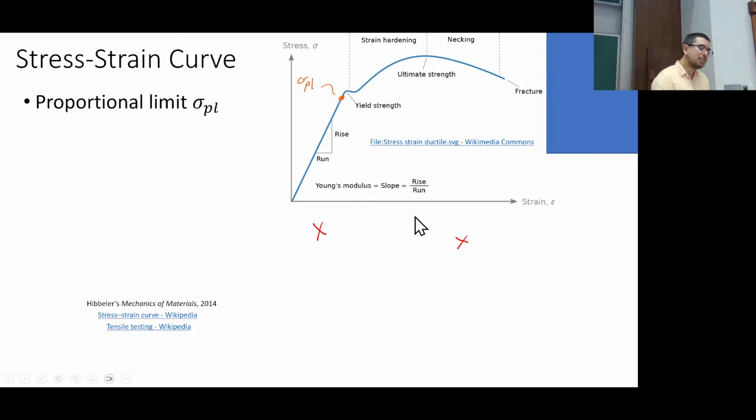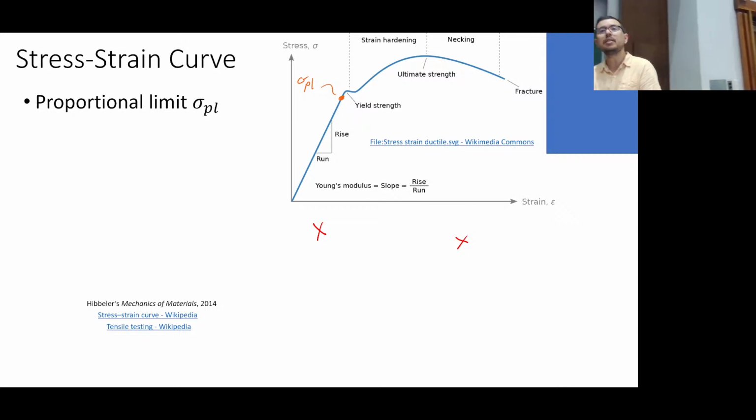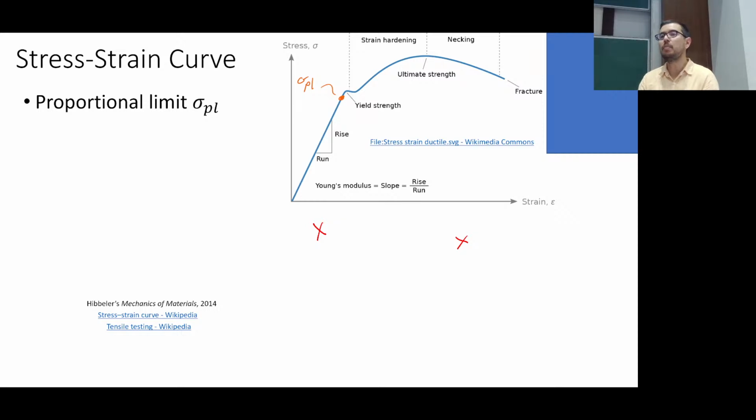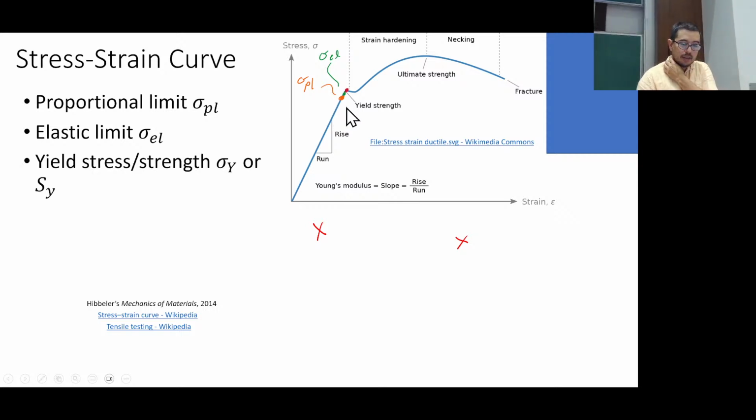What's interesting here is it's the same thing. We typically are applying strain to the systems and looking at the stress. That's just how these things are set up. So when you go to the lab, you're going to be applying strain. You're going to have a crank, and you're literally going to turn the crank, and that's going to provide the displacement. Then we're going to have a load cell that measures the force as we apply that displacement, and we are going to get to this interesting regime, or this point.